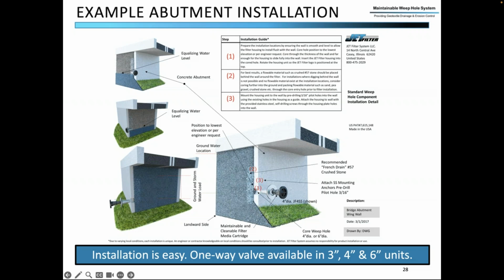Sometimes there's very poor backfill, so there are some other techniques to get some better permeable backfill. What you're seeing here is new construction, so this all looks good, but there are techniques to get stone into an existing structure to help the water flow if the backfill is poor.